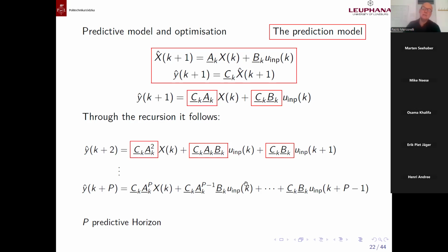And here it is not a square matrix because we have three rows but two columns in our matrix, because we have just two U. Because we are shorter in terms of U, let me say. Just two U if you have the control horizon with two dimensions, but three rows because this is determined by the prediction. Let me see if I made mistakes, but I don't think so.